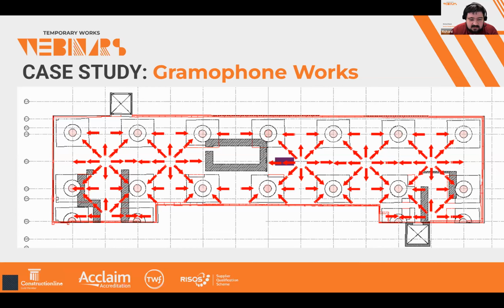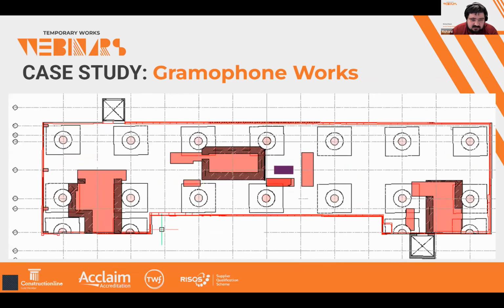So what we did to consider all these load paths was we looked at where these red lines that I've drawn on this picture are interrupted. Where they're interrupted, you're interrupting the load path, and you need to consider how you're going to support the slab when its load path has been changed. In some locations, the load path will be diverted through and around the slab that's remaining.